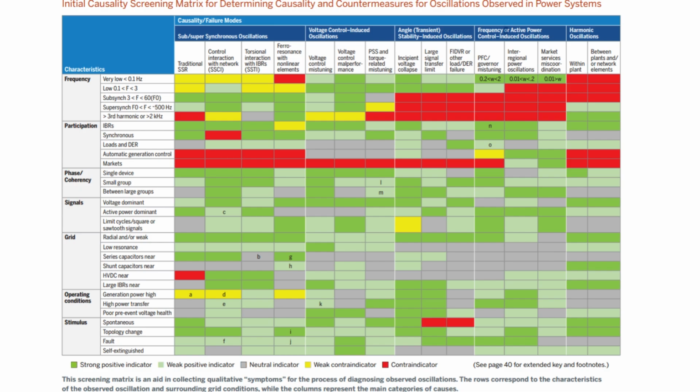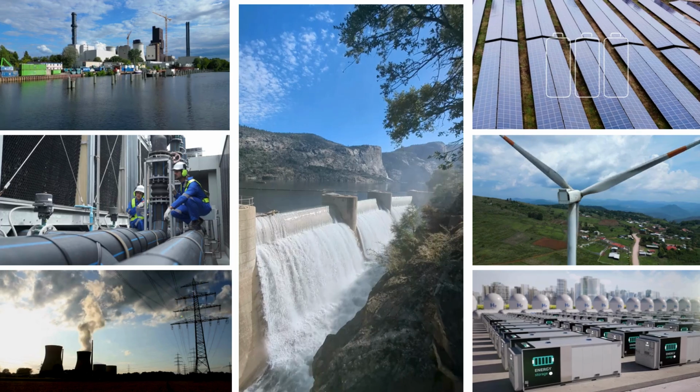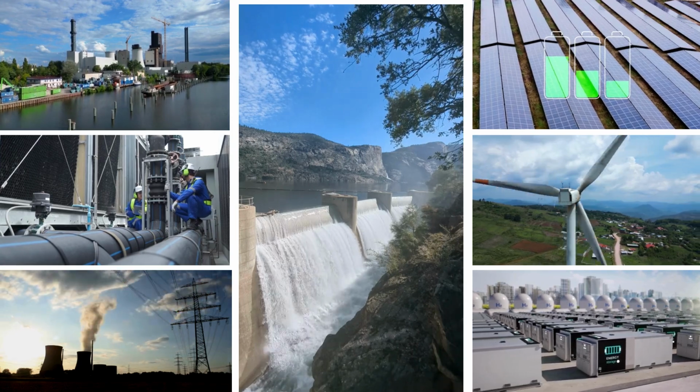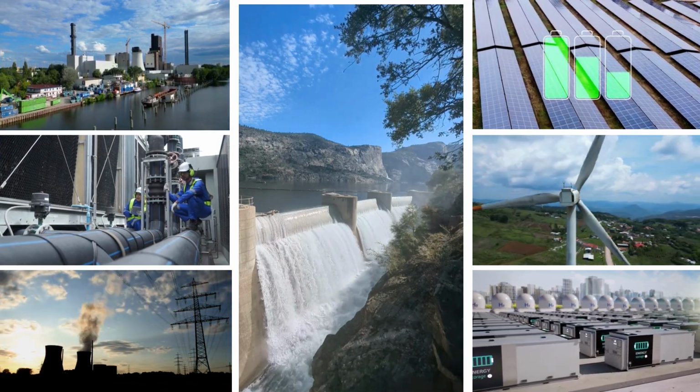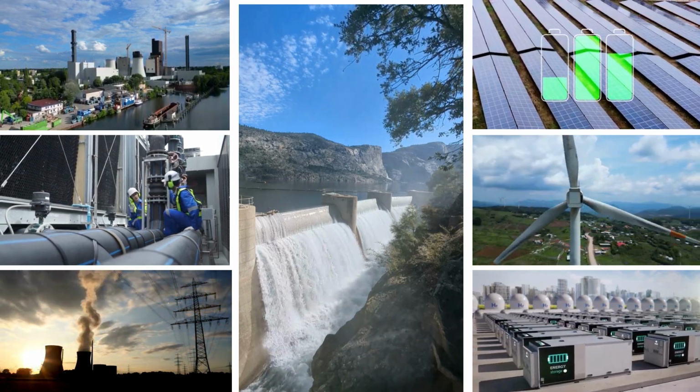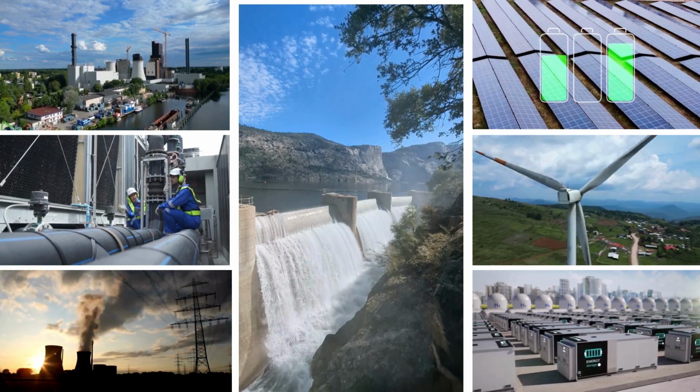And we noticed something quite important, I think, that the really dangerous situations, sustained zero damping, and especially the growing negative damping oscillations, often point back to vulnerabilities in the grid's control systems. Right, either a controller malfunctioning or an unexpected resonance effect happening. Exactly, which raises a really interesting question to perhaps leave you with, considering how absolutely critical damping and control are for system survival, especially as we integrate more complex, fast-acting power electronics from renewables and storage?